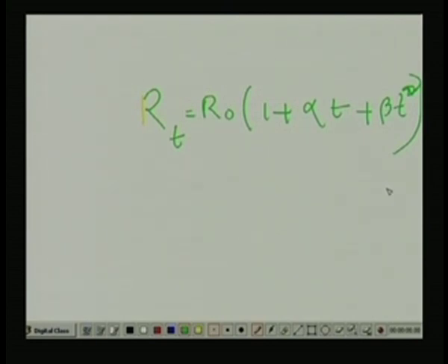So, in this type of situation I can approximate like this, because higher terms like gamma and all these things will be quite small and can be neglected. The amount of nonlinearity introduced by higher order terms will be very little. So, if I take it up to beta t squares, it is more than what we need for accuracy, as we have seen, 0.76% of the full scale. It is quite small. So, up to beta, that means up to the second order t square, is enough, right.